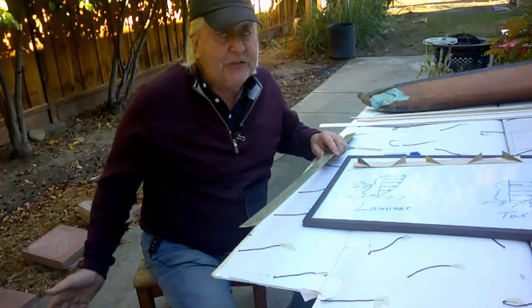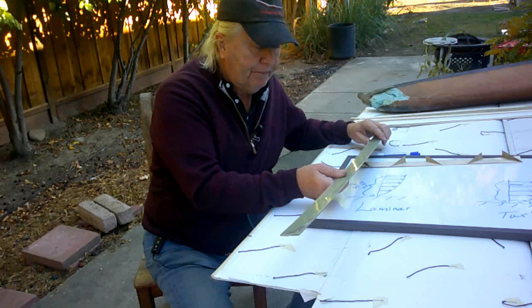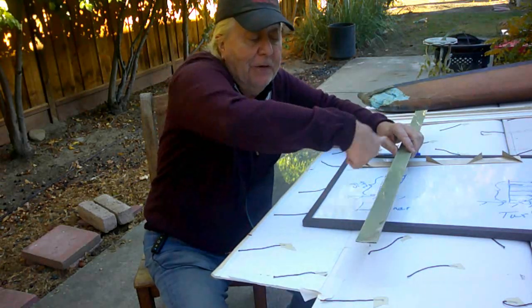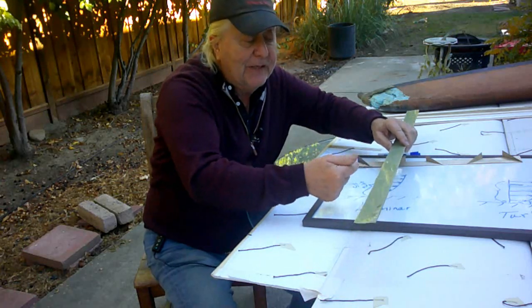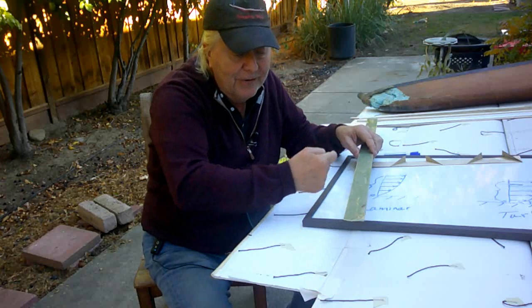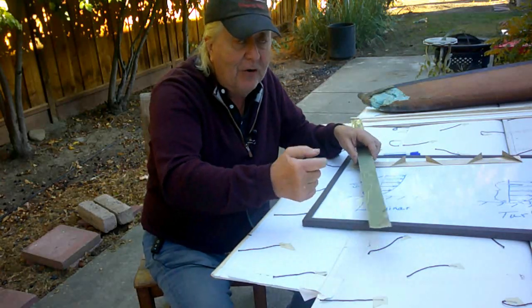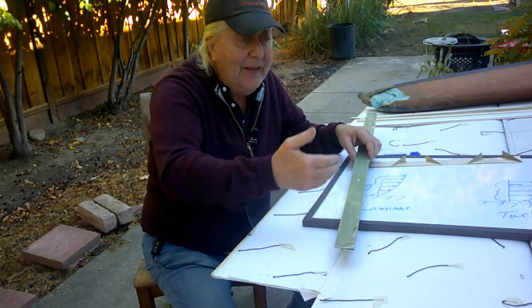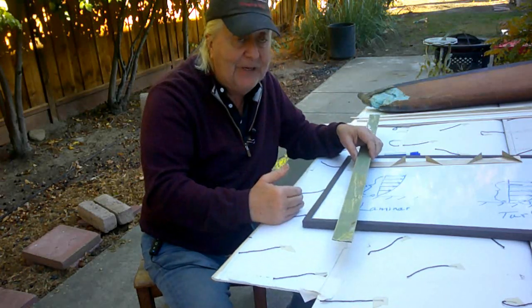It's just another spoiler. But you notice the way that I have my finger going. It's going this way. The flow's going this way. And you get that little vortex like this. Model airplanes use something similar. They'll put a wire on two posts above the airfoil, and you get a von Karman vortex street coming off the wire, and that pulls energy out of the free stream and takes it down to the boundary layer.